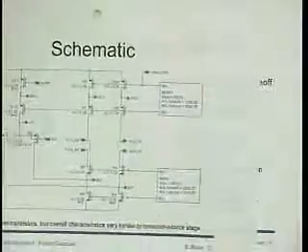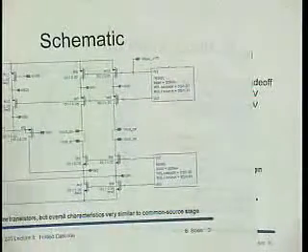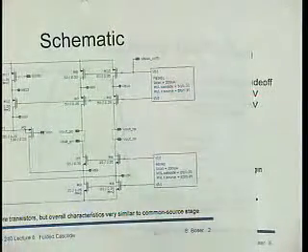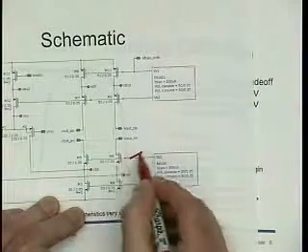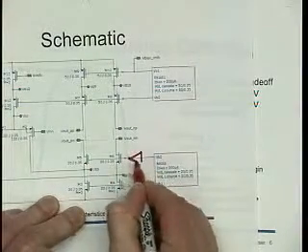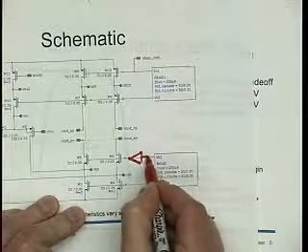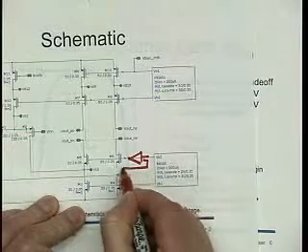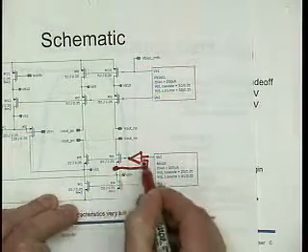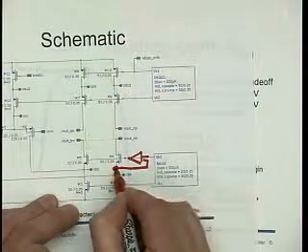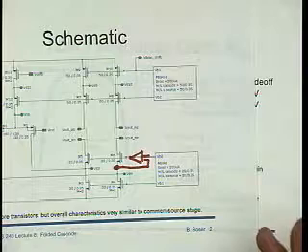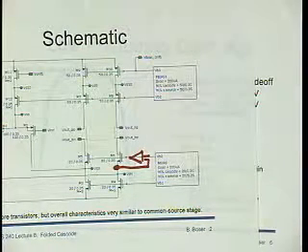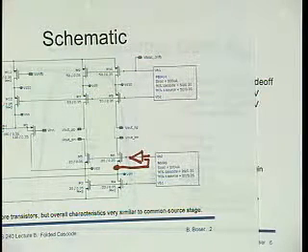Here's the other cascode. If we use a gain boost amplifier, there would be two separate ones, right? This wouldn't be connected anymore. Better not. So the bias, and then wrap it around here. Invariably we put extra capacitance on this node, and so we would get a little bit of a hit on phase margin. Again, if we have a fast technology, no problem. If it's a slow technology, then there might be an issue.